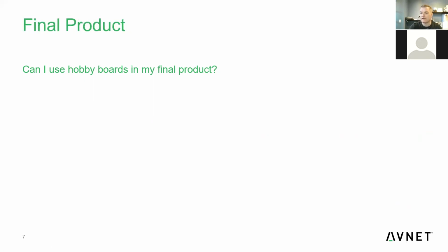And the main reason for that is, for one, I would say the requirements and everything that were put on those boards were not for it to end up in a final product. So things like environment, right? Being inside, so over a particular temperature range, being inside plastics has some constraints on electronics. These boards were not designed with those things in mind. Connectorization typically presents a problem, right? Most of these boards have some type of connectors coming off them.